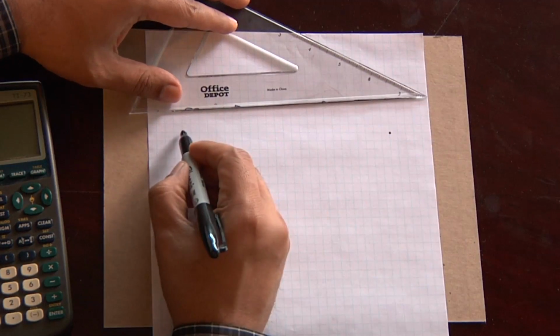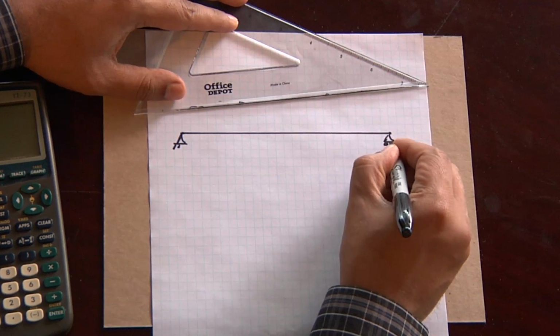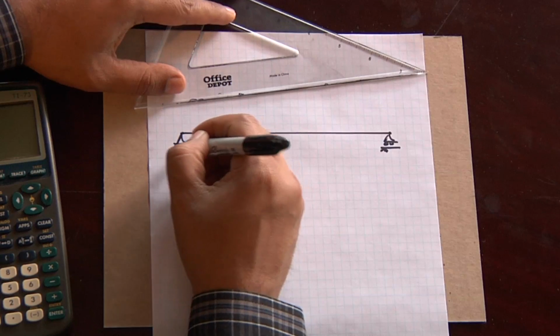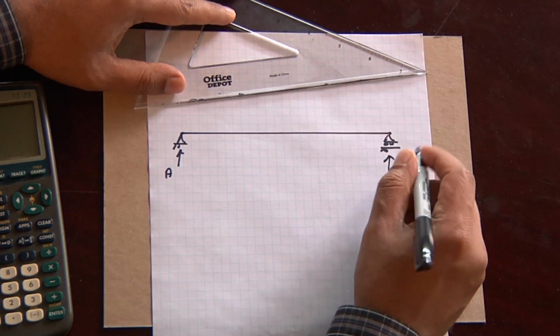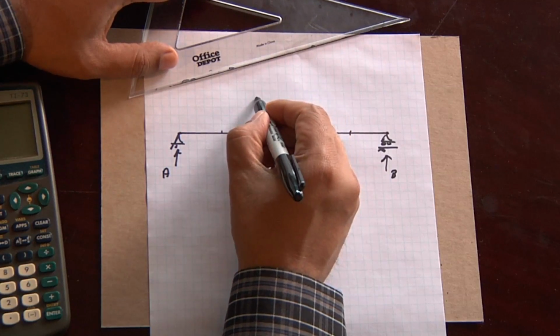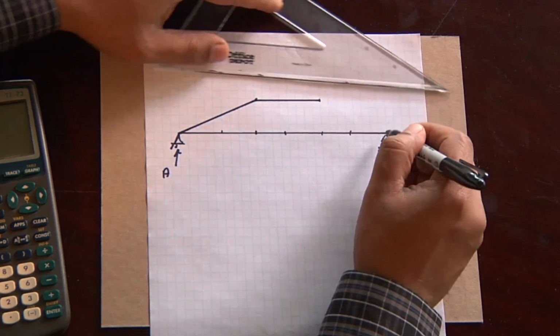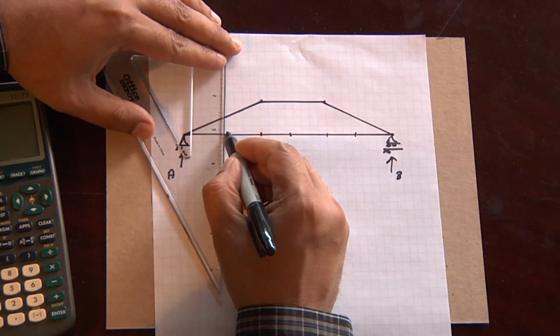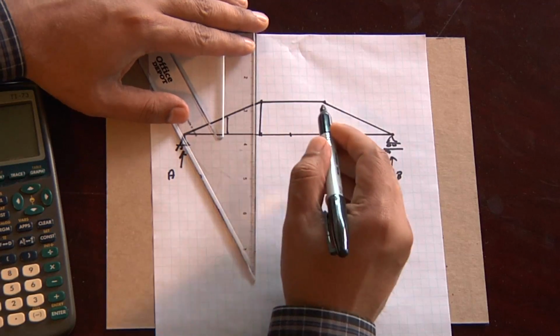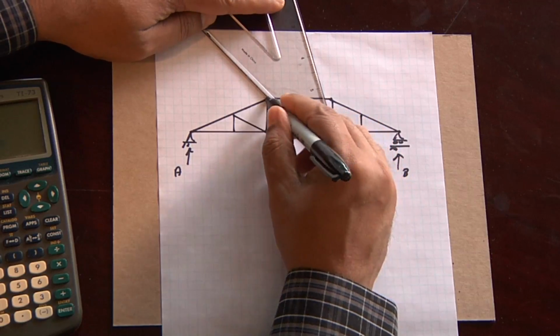Let's take a look at a truss which is a bit more complicated than the last example. And so this truss, we have statically determined two reaction points, A and B, and we have multiple bays. We have 1, 2, 3, 4, 5, 6 bays. Even though I'm not drawing it exactly to scale, they're supposed to be equal, but that'll be okay for purposes of this class. So we have our top chords, our bottom chords, diagonal chords,